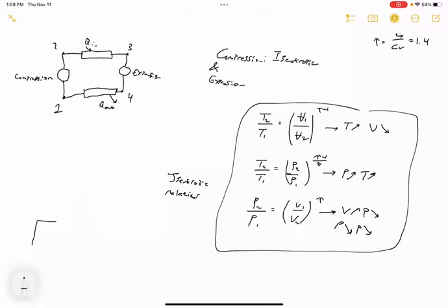So we have 4 states, right? So we'll draw 4 different cylinders. In the first state, we have the piston right over here, and the gas is inside the cylinder. We compress the fluid, so we move the piston all the way up, and now the fluid is in this much smaller area, and we're at state 2. And then we have this heat addition. When the spark plugs fire, the piston still has not moved. It's just that now we're adding in heat.